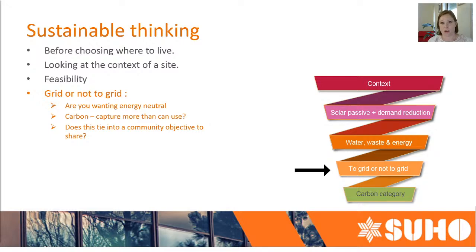Ensuring fresh air also helps. So if we go for a really airtight home, then we also might look at introducing fresh air into the building through an HRV system, which is heat recovery ventilation. It recovers the heat so that we're not losing the performance inside of the building too.